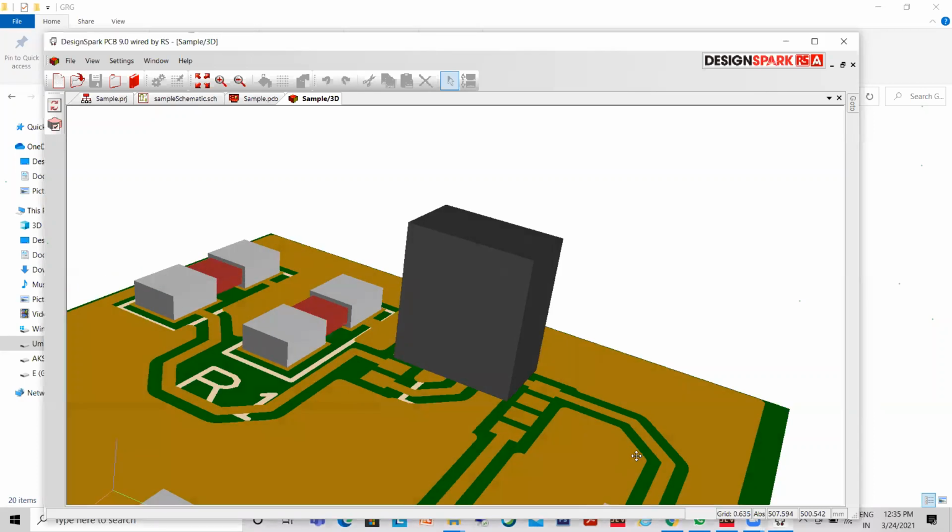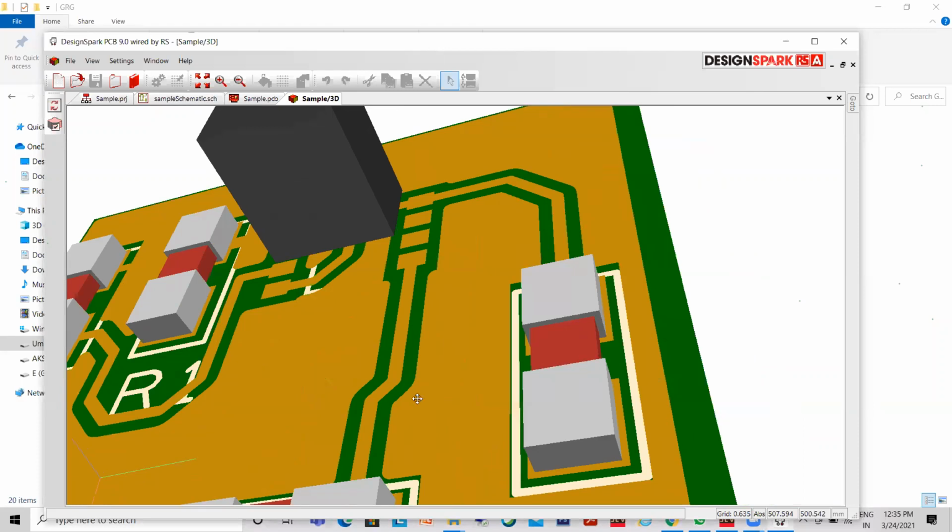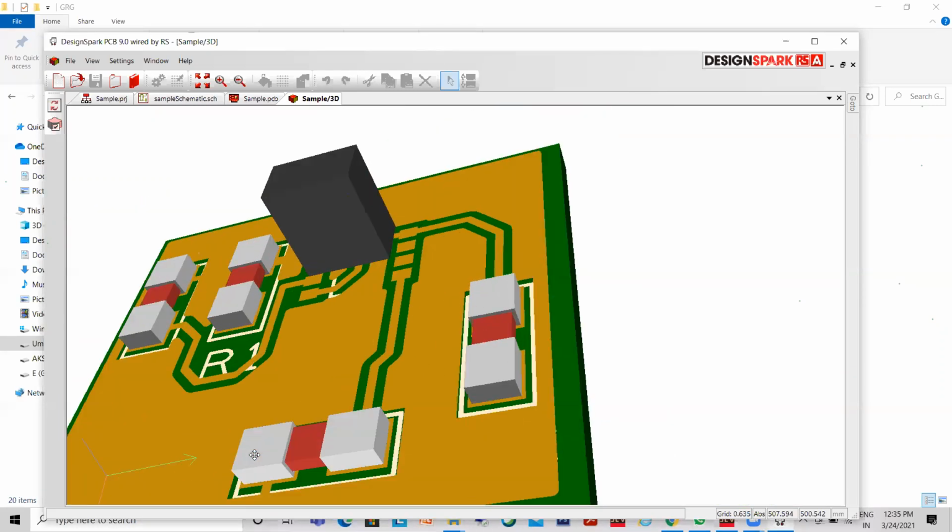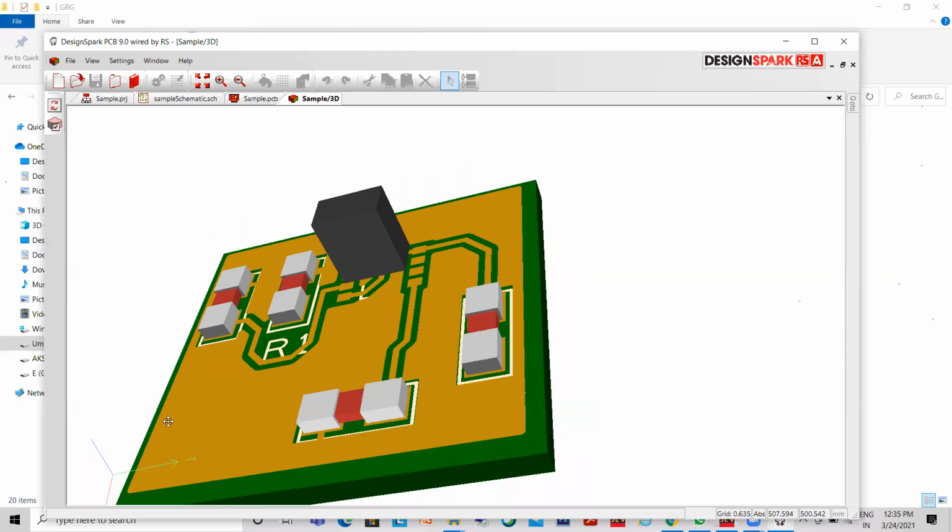So actually, if you see, this is actually a ground pin. So this has to be connected to this pin. Actually, this is ground, and this is also ground. So instead of making the trace connections, I am pouring this as a copper, and this copper pour is connected to this particular connection. So this is called a plane concept. So this plane has many advantages in it. So that will be a separate topic. So as of now, the plane is for making the connection between the components. So that is the concept.